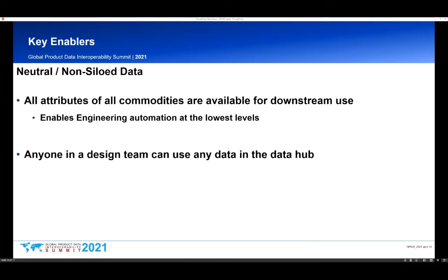By far, the biggest enabler for all this automation is our use of neutral data. When I say neutral data, what I mean is that it's data that can be consumed and interpreted from systems outside of the one that created it. So an XML file can contain data that can be consumed by any application. But a measurement taken interactively in CATIA by inspecting elements within a model is maybe less accessible. By forcing our critical design attributes to be managed in a neutral data format, we're able to parse them into numerous systems for our analysis and design work.